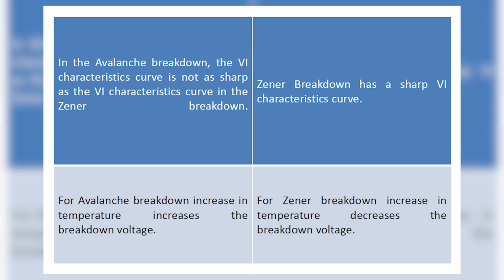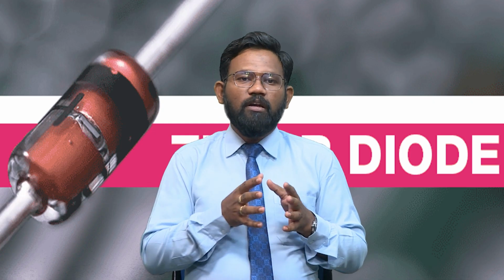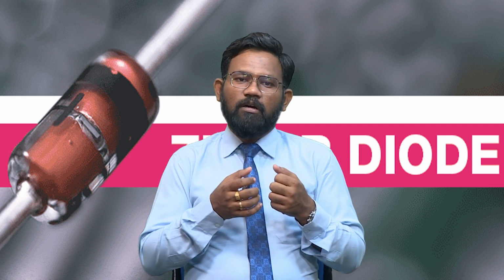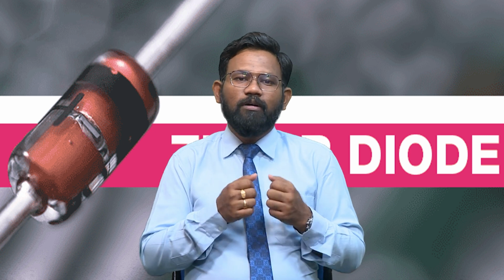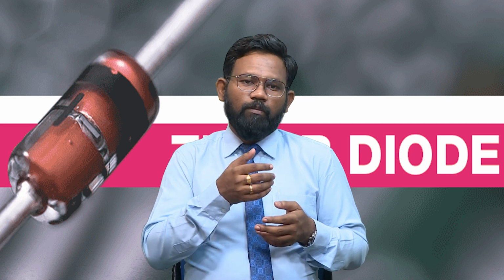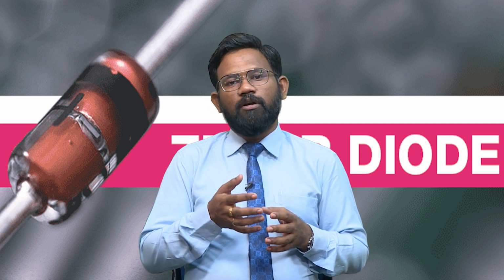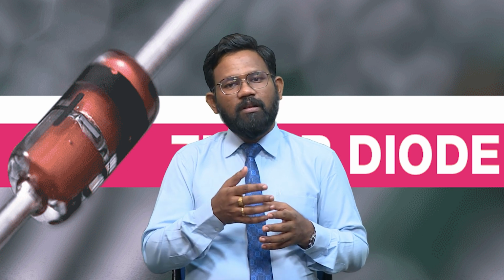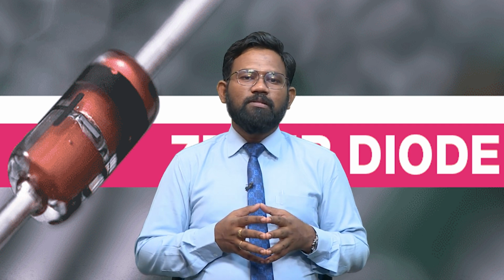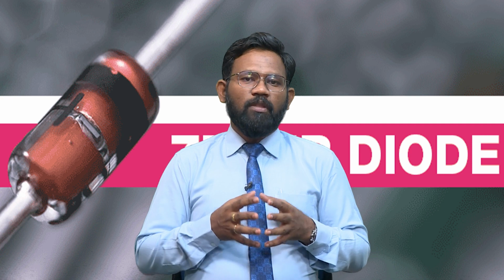For avalanche breakdown, an increase in temperature increases the breakdown voltage, and for Zener breakdown, an increase in temperature decreases the breakdown voltage. So this is also a main difference between avalanche breakdown and Zener breakdown, in which temperature plays its role in different ways for both breakdowns. In avalanche breakdown, if the temperature increases, the breakdown voltage will be increased, whereas during Zener breakdown, if the temperature increases, the breakdown voltage will be decreased. So these are the differences between the avalanche breakdown and the Zener breakdown.